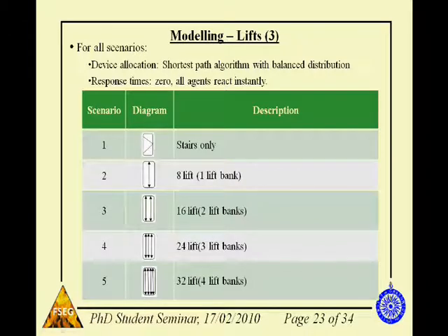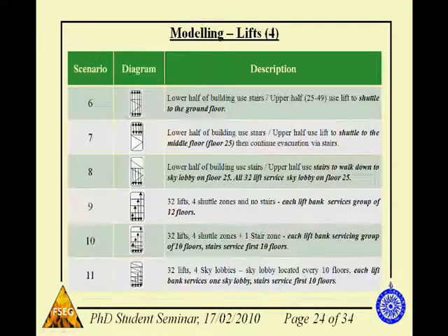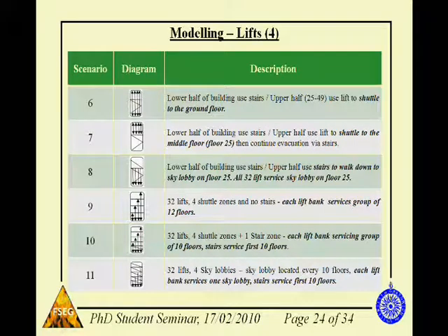After the stair scenario, the first 4 simulations looked at the frequency of different lifts being available and how this impacted upon the evacuation, gradually incrementing an extra lift bank with each scenario. The next scenarios we looked at using a combination of both lifts and stairs to evacuate different sections of the building in different ways. And again, we looked at the concepts of zoning and also sky lobbies in this.